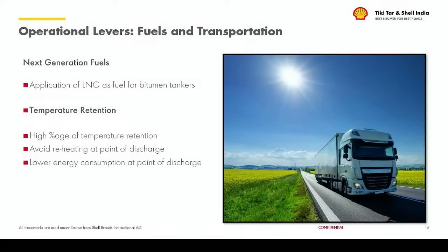Just lastly, I spoke about some technological levers. Now some operational levers. We transport so much bitumen, aggregate, mix. Some of the things we are doing, we are trying to move towards LNG, which is a much cleaner fuel than what we are using. Similarly, some of our bitumen and especially PMB trucks, which I request all the contracting fraternity to collaborate with us, we are now able to supply you PMB which retains heat to a much higher degree, where at your point of discharge, the reheating is avoided. And you know, the more cycles of heating you give to a PMB, the more the migration of properties happens. So lower energy consumption even at point of discharge.